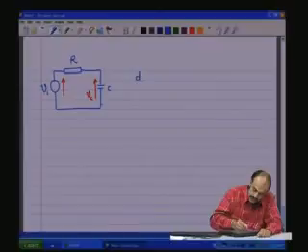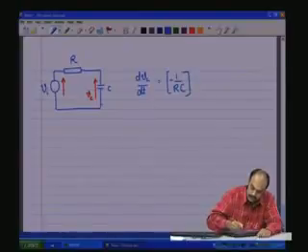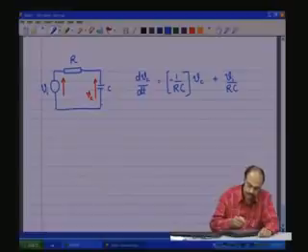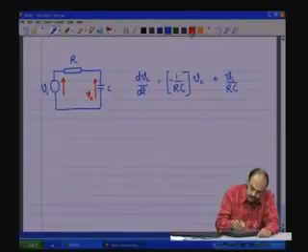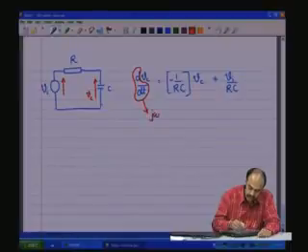So, the state equation is dVc by dt is minus 1 by RC into Vc plus Vi by RC. Now, the step is that for all the d by dt's you just replace by j omega.